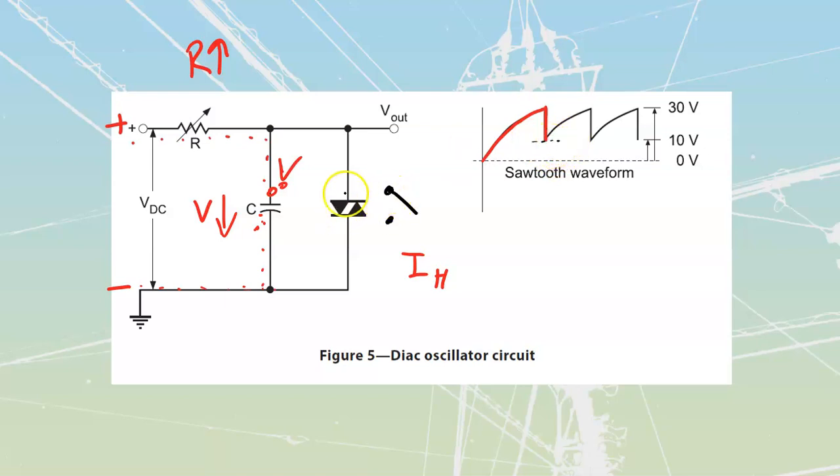And now this thing opens, which means that I'm going to continue to rebuild electrons there, rebuild holes over here, and my voltage once again starts to rise. And so I'm going to start to rise up here. We hit the forward breakover. Once we hit the breakover, boom, it drops, discharges the cap. It hits the value of holding current there and rises again, boom, drops, etc. So we are going to have this drop that's going to go back and forth from one to the other.